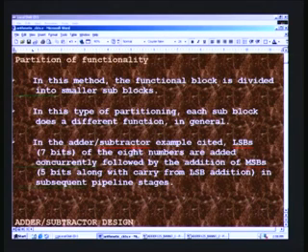In the add or subtract example cited, the LSBs, 7 bits of the 8 numbers, are added concurrently, followed by the addition of the MSBs, 5 bits, along with the carry from the LSB addition in subsequent pipeline stages. This is to say, we take only 7 bits of LSB and add them in the first pipeline stage and register it, that is in the first clock pulse.